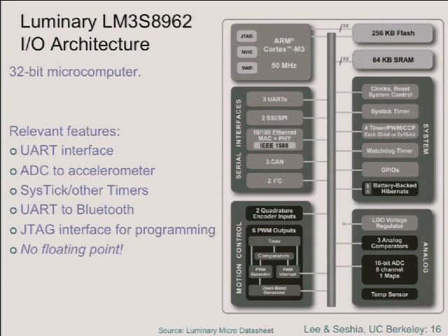So UART is a serial port interface. You can use UART to connect to Bluetooth. That means you can very easily get a serial port connection over a wireless link. It's a nice thing to do in lab exercises because it's relatively easy. If you want to get a wireless connection between two embedded system devices that don't have an operating system, using the serial port through Bluetooth is much easier than writing a TCP/IP stack on Wi-Fi.